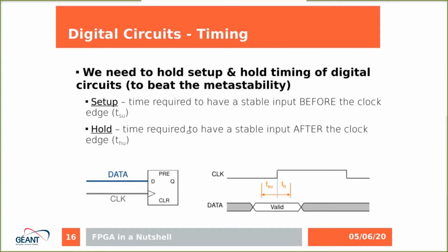As you can see on the diagram, there is a clock cycle, and before the rising edge we need to have the input data valid. And we also need to have the data valid after the rising edge.